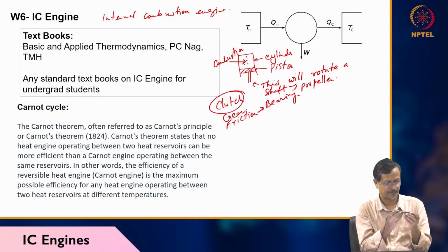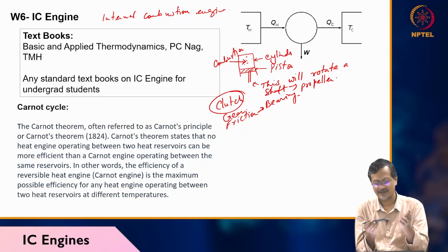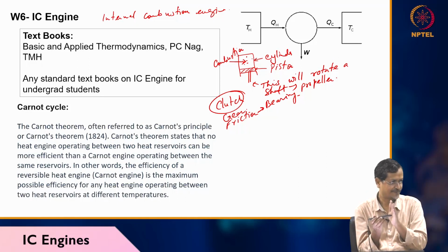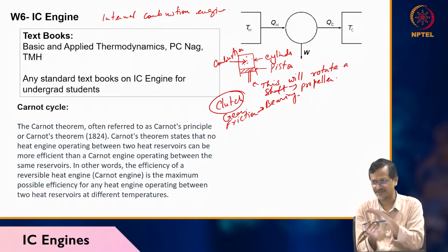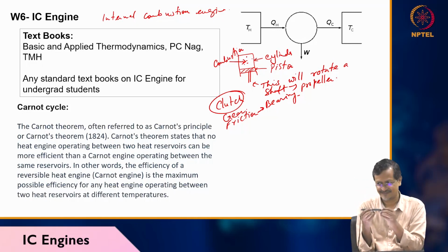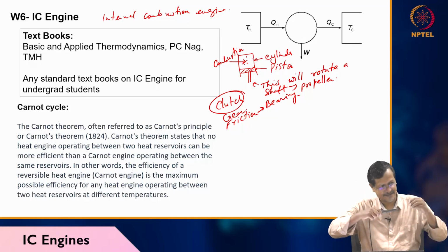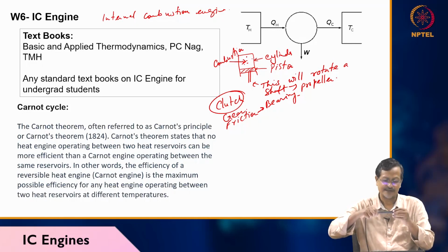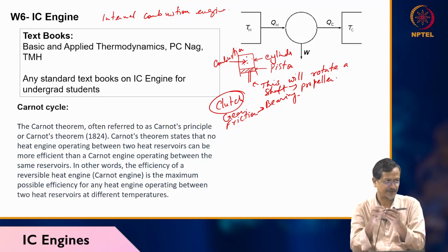When pushing water, because of Newton's third law, the water will push back with the same force but in the opposite direction, right? That means the shaft will get another force, an axial force. One torque is being transmitted, but it is getting axial force also. But you cannot transmit that axial force to your engine.